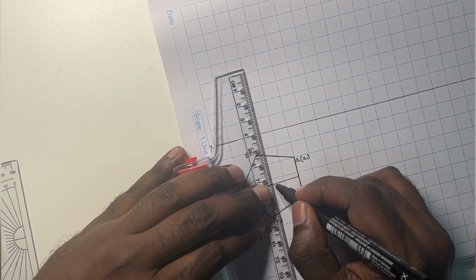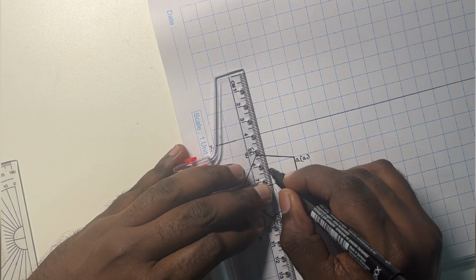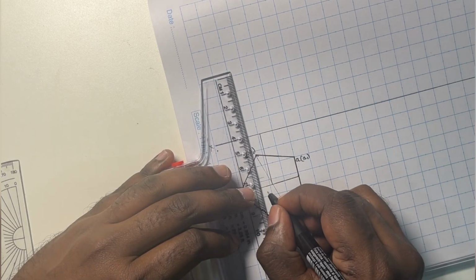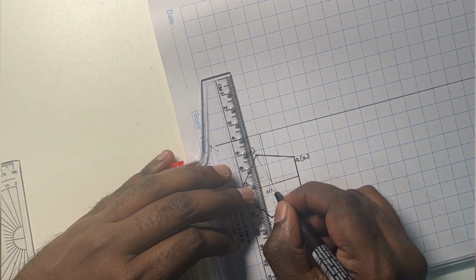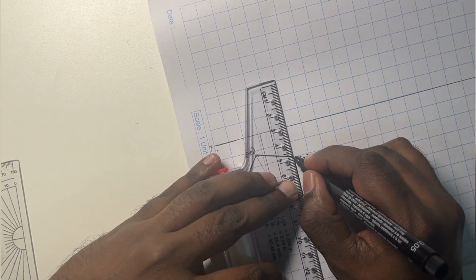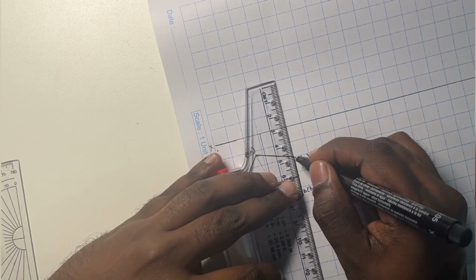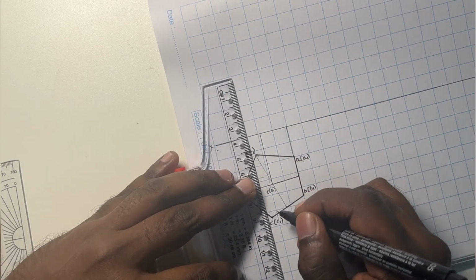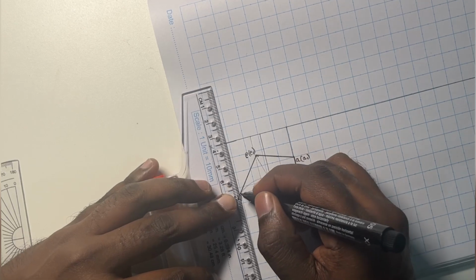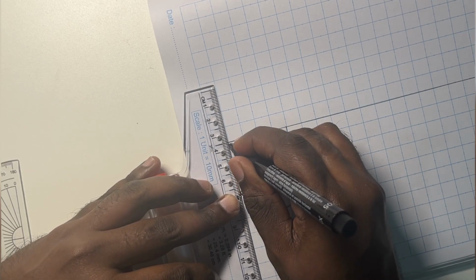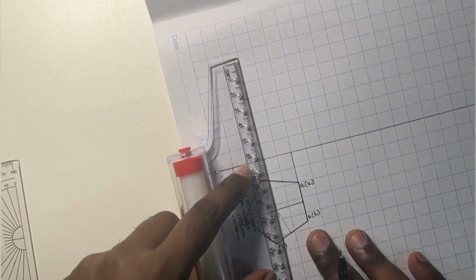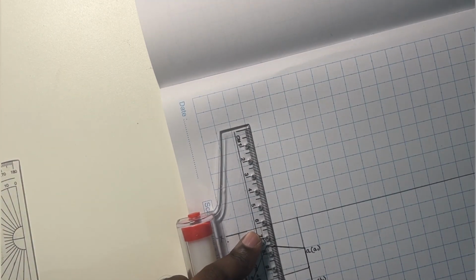So this marks the centroid of the prism from where the axis is going to originate. So this is O1. So O is the center point of the top face, O1 is the center point of the bottom face of the prism. Similarly, from the other edges, let me draw the projection lines. So C and E will have a common projection line and a separate projection line for the corner D. So now, as per the problem statement, the axis measures 60 mm.